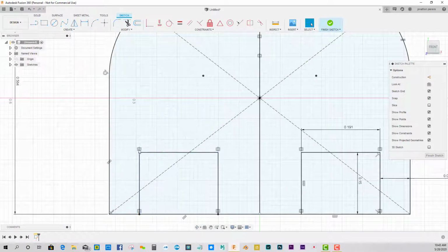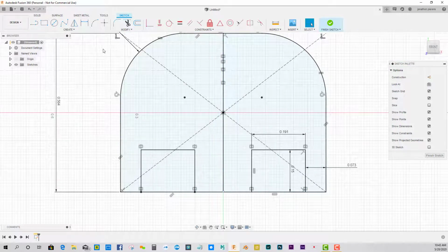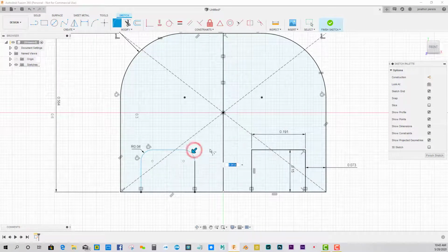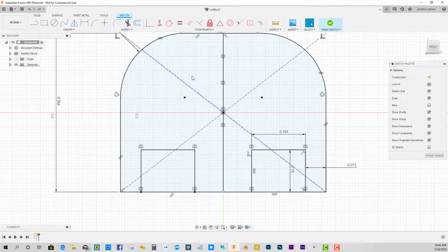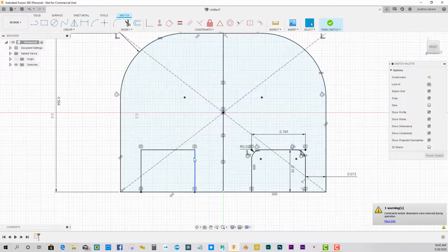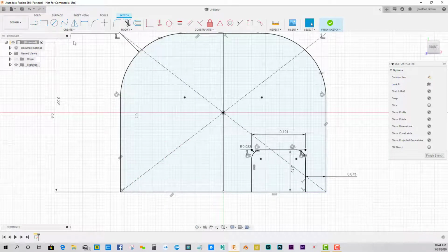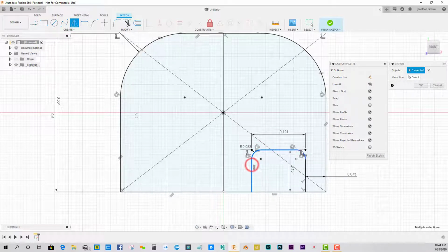For these center legs, I'm going to give them a radius, which will make it easier to machine, and that radius is going to be 0.0325. We'll grab our fillet tool and select all of them. Actually, we'll do it to here. It should move over to the other side. If not, it's okay. Do it here, 0.0325. Boom. Then I'll delete this, because I should have done everything on this side first and then mirrored the complete version. So you get to see me do it again. Mirror line, that center line, right over to the other side.